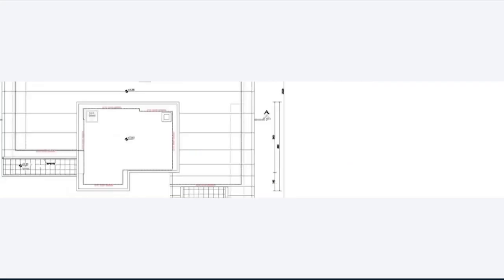Okay. We talked about the roof, the information given to you: those dashed lines must be there, and those setbacks and gutter information. If it is cylinder type, it will be like that. If you use a gable type, it should be like that. So don't forget, this is for gable type, this is for cylinder type. Don't mix them with each other.